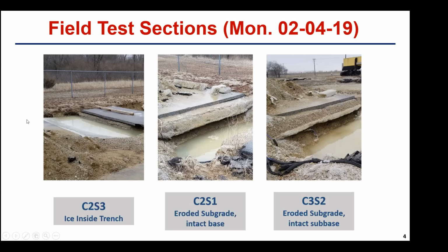So IDOT reached out to us with the idea of why don't we complete that project that was done with the field performance and do some durability testing, just take advantage of those test sections, get some field samples and test them for their durability in the lab, and see how durable those samples are and what numbers we get for soil cement loss, which is what defines durability in those tests.